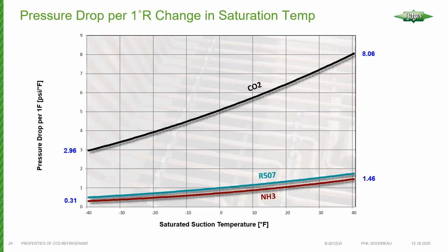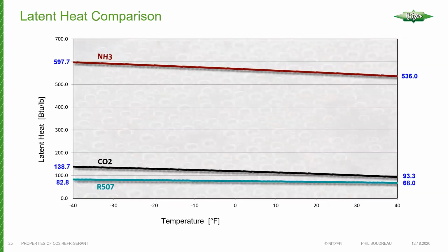So as always, things are more critical when we get into the lower temperatures, whether it's CO2 or HFCs and what have you. But you can see quite a difference between CO2 and other refrigerants here in terms of the effect of the pressure drop.